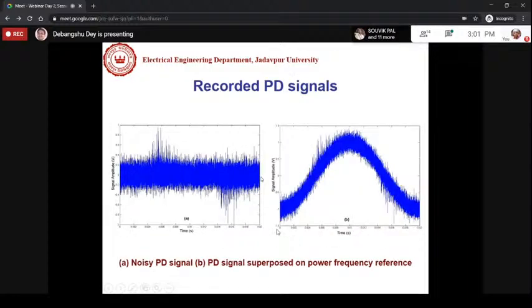And if we record it, you can see these are the kind of signals we have recorded, the real life signals that we have recorded in our laboratory. On the left side, please follow the cursor, you can see there and there. At these two positions there are certain higher amplitudes, and over the base noise there are some oscillations all over, and certain portions with some small higher portions up there. So higher amplitudes are there, and they indicate the occurrence of partial discharge.